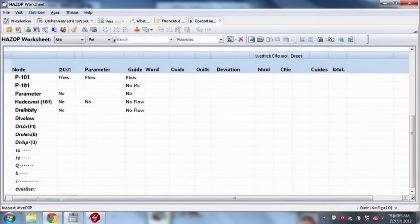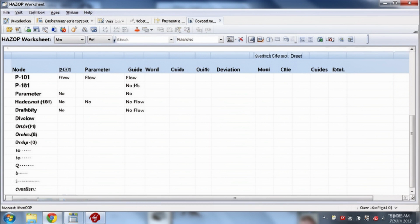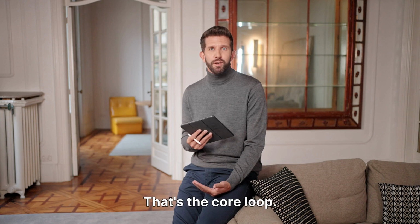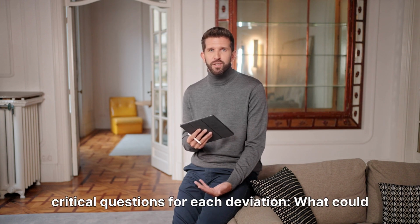Let's put it in a worksheet. For node 1, our pump suction line, we apply "no" to the parameter "flow." The deviation to be analyzed is "no flow." We've now identified our first potential problem to investigate. We do this for every guide word and parameter combination. That's the core loop.